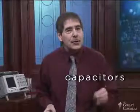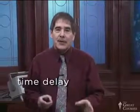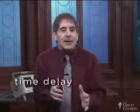What capacitors do in circuits, though, is this: you have to flow charge onto a capacitor in order to charge it up, in order to change its voltage, because charge and voltage, remember, are proportional in a capacitor. Capacitors fundamentally introduce a time delay into a circuit. So that's what capacitors do. They affect timing in circuits, and for that reason they're used in all kinds of applications.